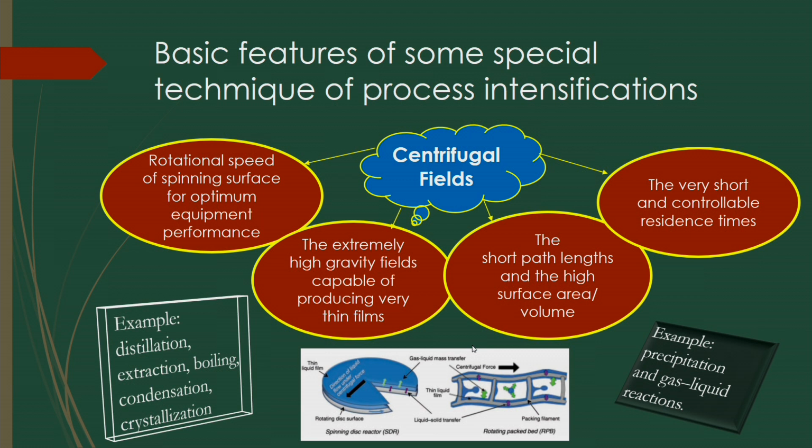So you have to control the residence time of the gaseous bubbles or any substances or fluids to get more mass transfer. Sometimes for fast reactions it may not be required to get more residence time. In that case you can operate the upflow reactor or upflow bubble column reactor for fast reactions, whereas where slow reactions are involved, you have to increase the reaction residence time of the fluid particles by downflow operation.